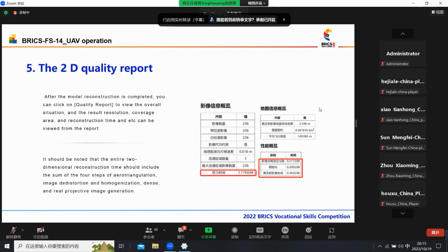If you are in the reconstruction process, or if you want to add a new format or modify the coordinate system after reconstruction, then keep the intermediate folder. If no additional action is required after reconstruction, manually remove the folder to free disk space.